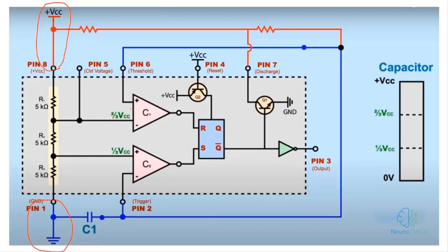It means that if we follow this blue line, these blue circles here, if you pay attention, let's say, for example, there's a particle or that voltage coming from pin 6. It moves down this way and then over here, and eventually it connects to ground. So the resistance I mentioned here, where pin 7 is connected to pins 2 and 6 through this resistor, it won't take that path anymore because it's a longer route. You see, if it comes here, one path would be to go this way and for pin 6 to go through this resistor, but obviously it will choose the easier path to connect to ground.